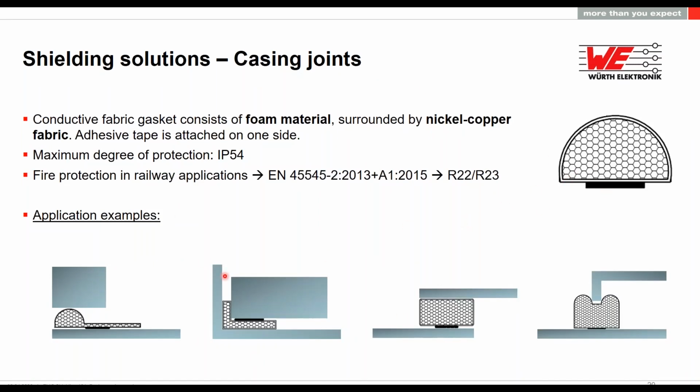They can be cut like this one in a really thin square, and then stamped in order to have the shape of an HDMI connector. In this way, when you connect the HDMI to the device, you ensure that the whole grounding of the HDMI cable is in contact, with 360 degrees of connection, to the ground of the final device.